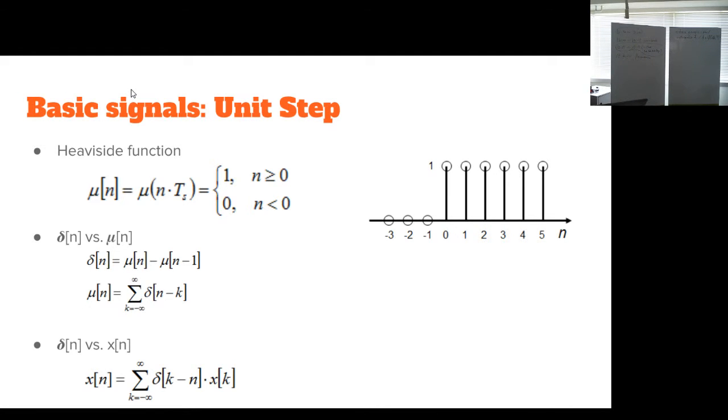Another important signal is the unit step, because, well, it's just the sample form of the unit step function or Heaviside function in the analog world. And this one now resembles a square wave. To test systems in the laboratory, well, that's probably what you usually do. Device under test, you take the function generator and see with the oscilloscope what the output waveform looks like. So basically, this unit step function is just a sampled Heaviside function. A useful test vector for testing systems.